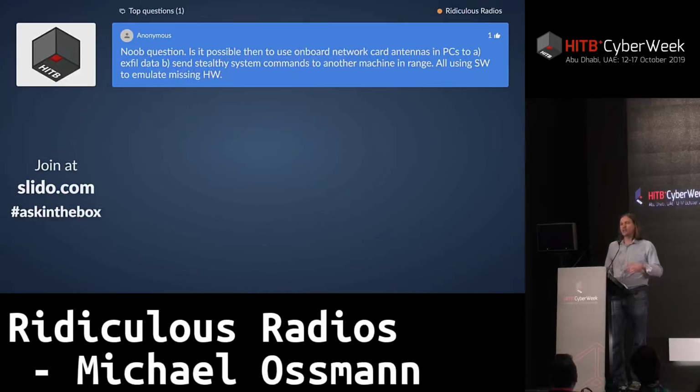And you'd be better served looking for a different funtenna, some other electrical signal, like maybe a wire that goes from the main board into a sensor, like a magnetic sensor around the edge of the laptop. Or an LED that's an indicator most of the time, but you could repurpose. You'd have better luck looking for a funtenna that wasn't originally intended to be an antenna, I think.